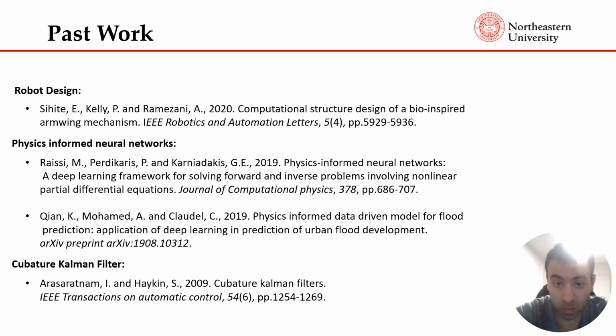In this work, we combine neural networks with Cubature rules to learn aerodynamic forces acting on the robot. We use tools from physics-informed neural networks and the Cubature-Kalman filter to design a recursive algorithm that trains neural networks using Cubature rules. We build on top of previous work which designed the robot by Ramazani, physics-informed neural networks by Raissi, and Simon Haykin's Cubature-Kalman filter.